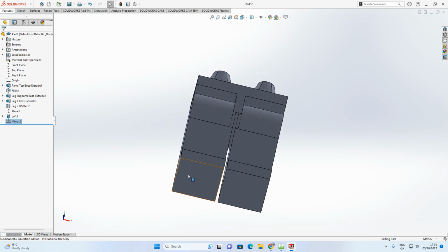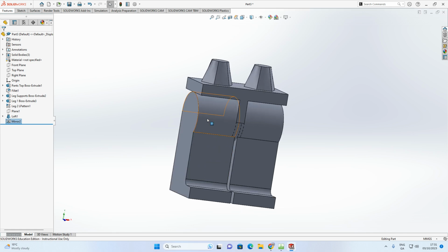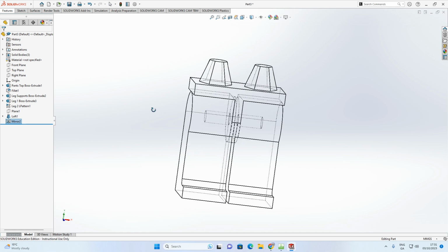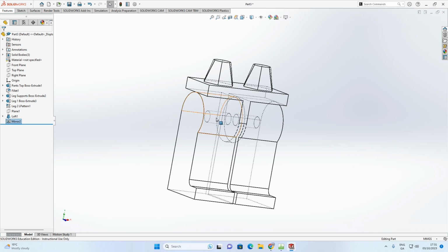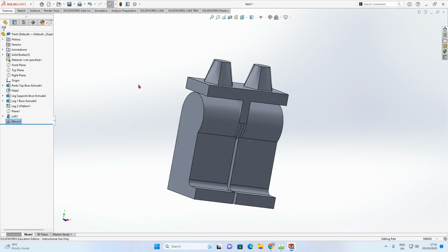All we're going to do is add on maybe little holes here where usually the Lego man would attach on. And we're also going to add in holes in here for the legs, where obviously that should be joined in, because we didn't create those yet. Even though it's obviously inside there, if I go into this view here, you can see it's going inside the object, but really I haven't actually created the holes for those to be pushed through yet. So to do that, we're going to use an indent tool. So we're going to use an indent tool for the legs.